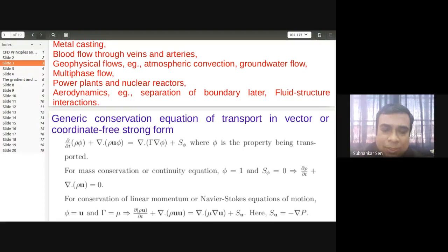In this equation, the second term is known as the convection term. This is a nonlinear term. Okay. So the format which we have written is known as the conservative form of the governing equation. So if phi becomes the velocity vector u bar, then this term rho u, if phi is equal to u bar, okay?